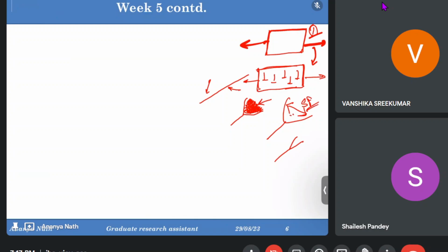Okay, and the energy associated with this place is called the stacking fault energy. Now if the stacking fault has occurred, but the distance between the two partial dislocations is not enough for the solute atom to come and sit there, it means there is a high energy in that stacking fault. The energy is high. Why? Because these two dislocations will always try to catch up with each other again to get their original shape and size. This is why the energy is high.